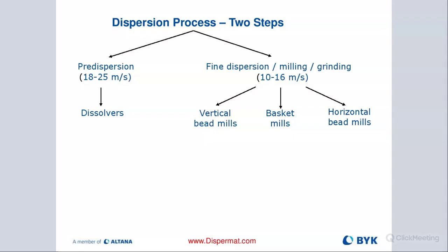Now, as I mentioned earlier, when you're at about 10 to 30 microns of particle size, the Cowles blade is no longer efficient enough to continue to further reduce the particle size. So we need something that gives us more energy and more power to really break down these aggregates and turn them into primary particle size. For that, we need a milling system.